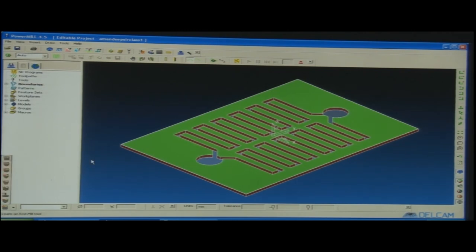Now, what are the tools here? The 3 points that I mentioned before: the machine tool, the cutting tool and the job. So, let us talk about the cutting tool here. What are the options? We have an end mill tool. What is the purpose of the end mill tool? It does the roughing. Most of the material is removed using the end mill, then the ball mill is generally used for finishing, then the tip radius tool is there. This is also called bull nose, then the tapered spherical tool, then tapered tip tools, then we have a drill tool, that is, normal drilling is possible.